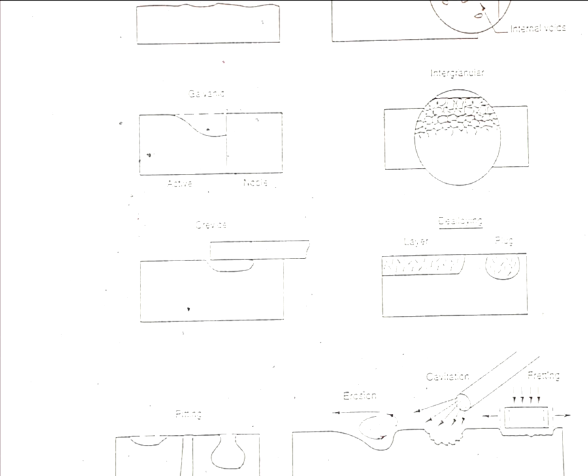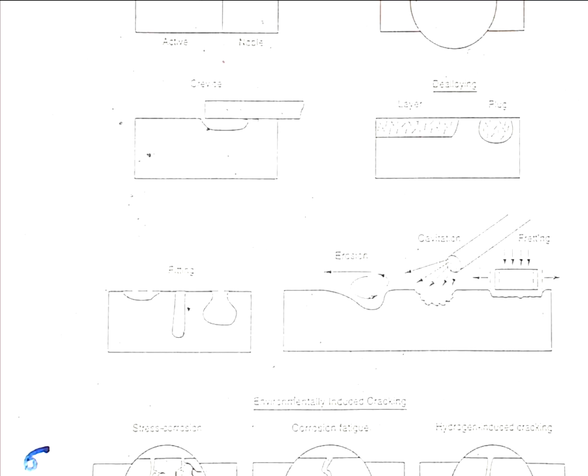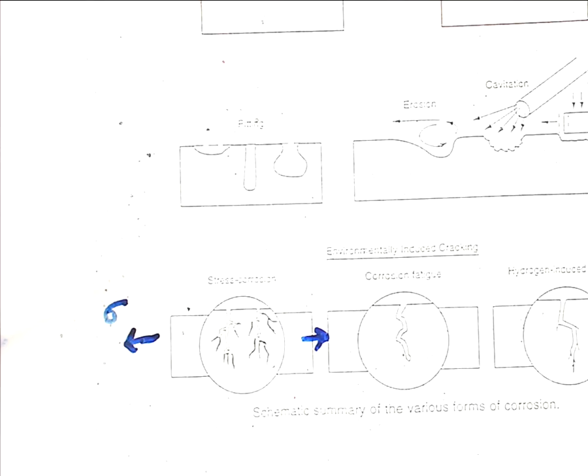And the reason for that is that there is, if you like, a resistance to current flow. So the bulk of the current will flow to the nearest point, and so you get the most of the corrosion closest to the cathode. And then we looked at some other mechanisms, crevice corrosion, where you've got a pre-existing geometry, pitting corrosion, where you have quite often oxygen differential or some coating effect that localizes the attack to a particular area on the surface.